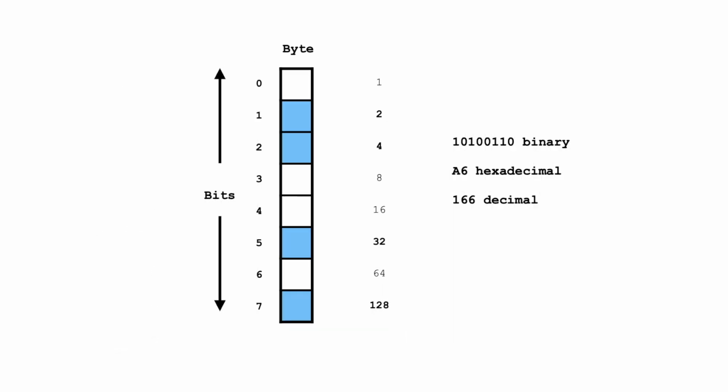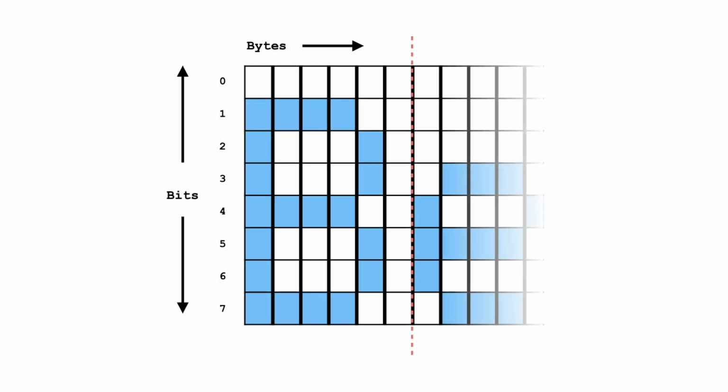If we look at one individual byte, we can see that the pixels are arranged vertically, with the least significant at the top and the most significant at the bottom. So if we wanted this arrangement of pixels, we could work out what the actual value of that byte should be. If we want to put some text or graphics onto the display, we simply put one byte after another to make up the display we want to see.